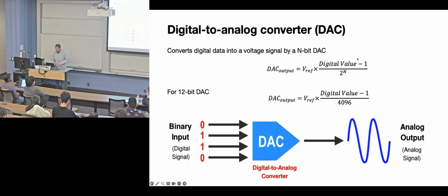And then the construction of that ladder that we did, where you had voltages here and binary values here, you just flip that for your DAC, where you have some binary values which would map to some analog voltage out. And that's essentially what these equations are implying through mathematics, showing that there's a conversion value. If you put some binary digital value in, and you know the number of bits of your DAC, plus your reference, you have to know what the conversion is from the high end, in this case the positive reference voltage, assuming 0 in this equation, it'll tell you what the analog output is.